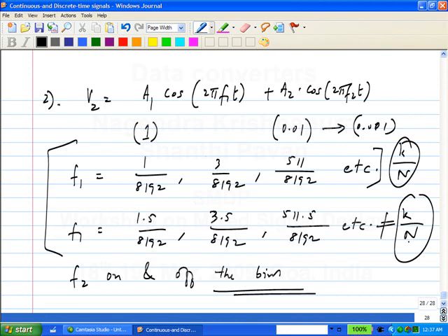You will have to check the strength at each harmonic, or use the dot Fourier analysis which is available, which is basically the same thing. It is doing FFT and checking the strengths. Approximately it is doing the same stuff.